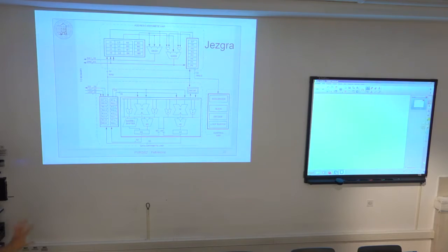Okay, now we come to the block scheme of the architecture of this Blackfin CPU. And what you can immediately recognize here are these two MACs. So MAC 1, MAC 2. We have these two multiply accumulate units.